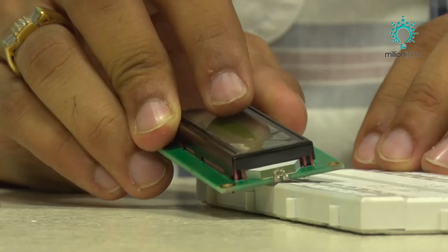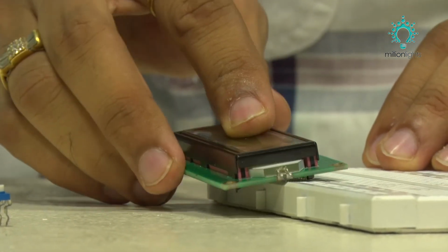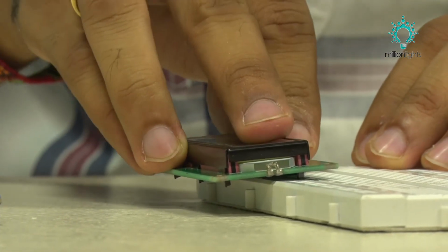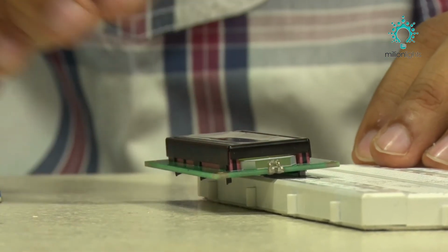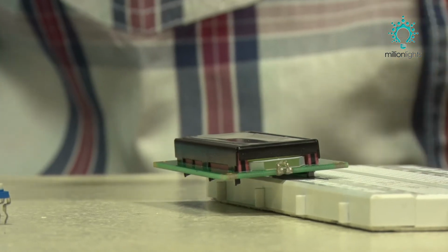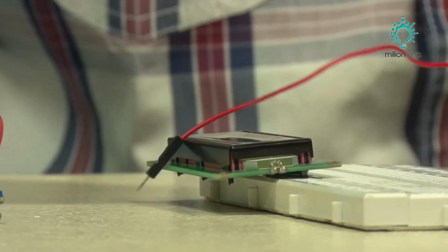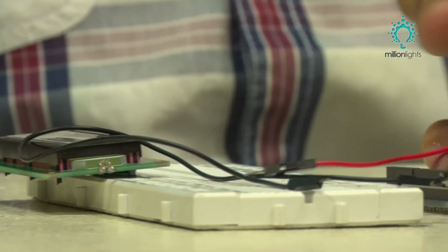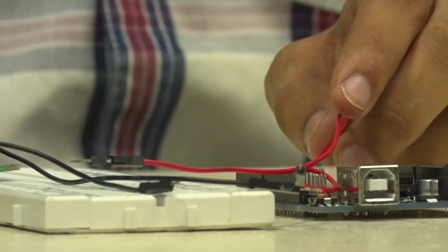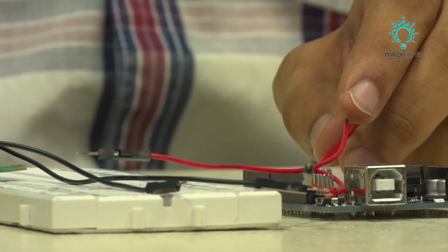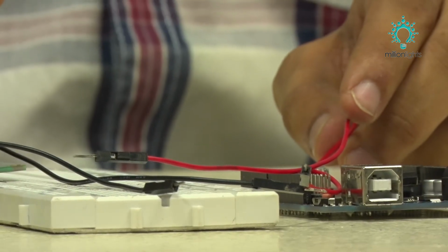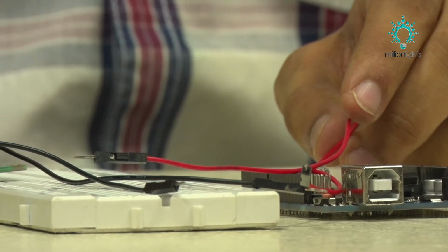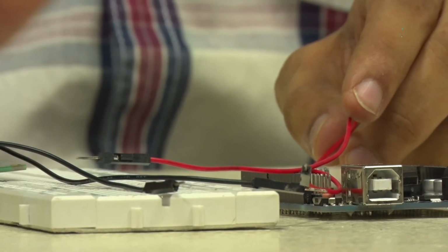First we start by placing the LCD onto the breadboard. It easily goes inside the breadboard without any problem. Now let's start making the connections pin by pin. Before that, I'll take black and red colored cables because I want to create VCC and ground rails, as there are a lot of VCC and ground connections required. If you use red and black, it is easy to identify, we do not make mistakes, and there is a reduced chance of short circuit.